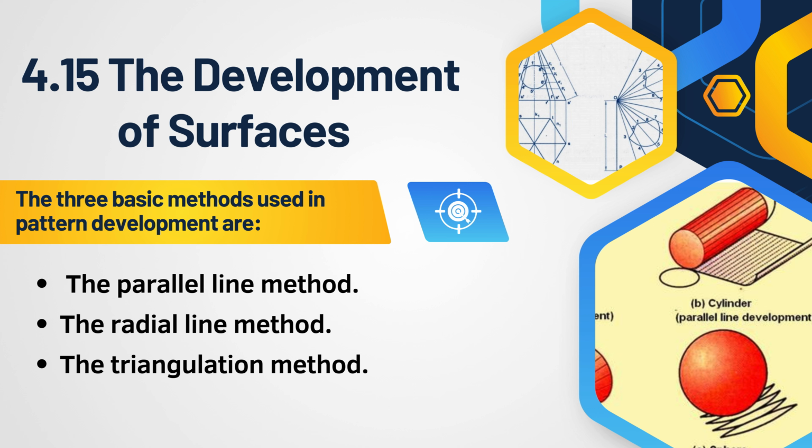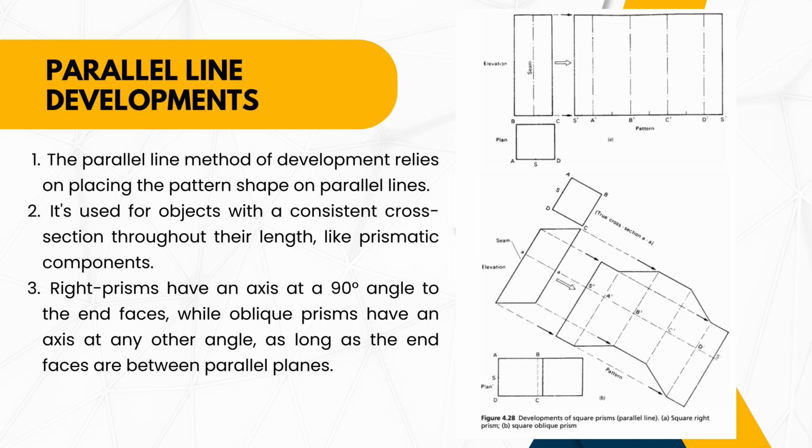And next, for the development of surfaces, we have three basic methods used in pattern development: firstly the parallel line method, then the radial line method, and also the triangulation method. Firstly, the parallel line development.